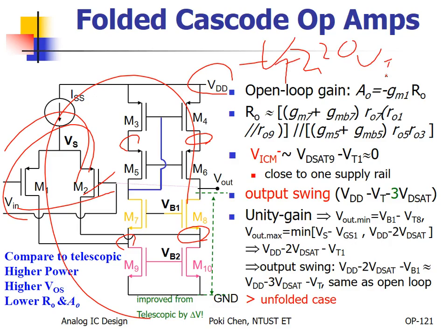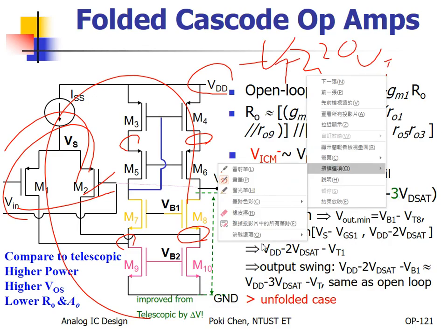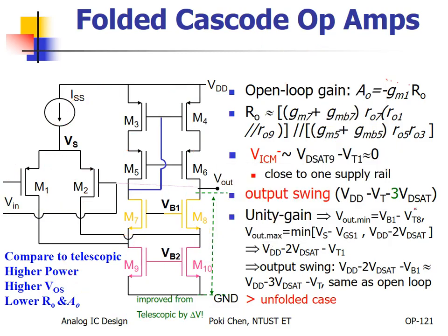If you connect both in parallel configurations, you get the rail-to-rail op-amp. It means, again, for N-type, it functions here. For P-type, it functions there. But they are connected in parallel. So your input can operate from here all the way to there. Right? The only problem is in the middle.